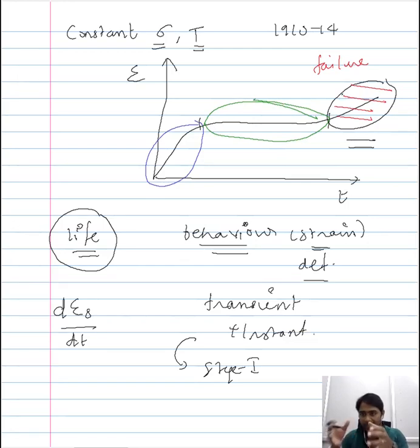So when you have a material that has been employed in an application for a very long time, and after a certain duration the material begins to deform excessively, and you see that this deformation is bothering other components in the application, then instead of allowing the material to fail, you stop the application and replace the material. That is how it is usually done in the area wherein high temperature material is used.